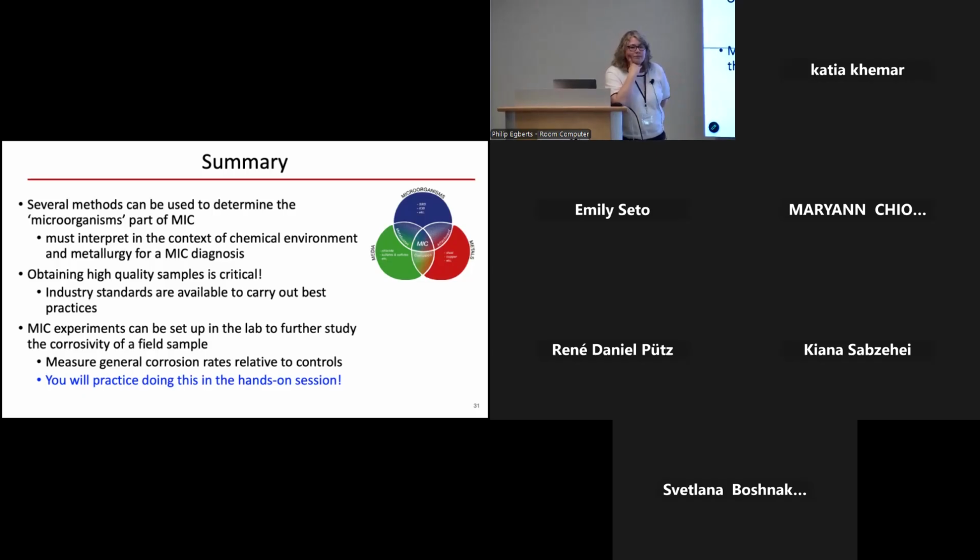Normally when we do weight loss, it's really important to choose the right pickling method for the right type of material. But here this is probably a good proxy. We've had the problem before where sometimes our coupons or beads weigh more than our starting weight, so we haven't been able to get all the residue off. Oxides are difficult to dissolve, either from the material itself or otherwise, so you have to use a pickling method, like increasing the temperature.